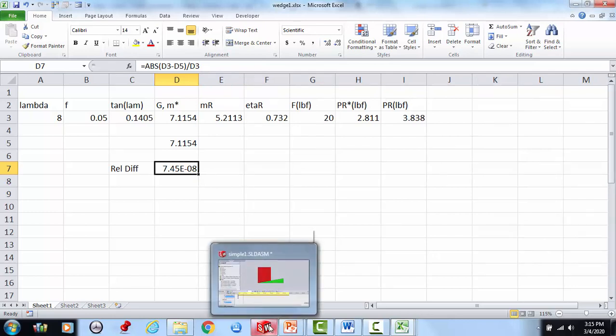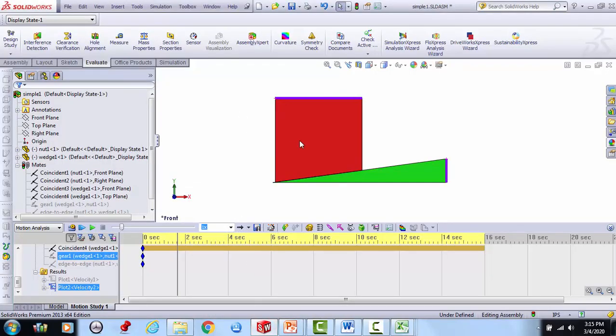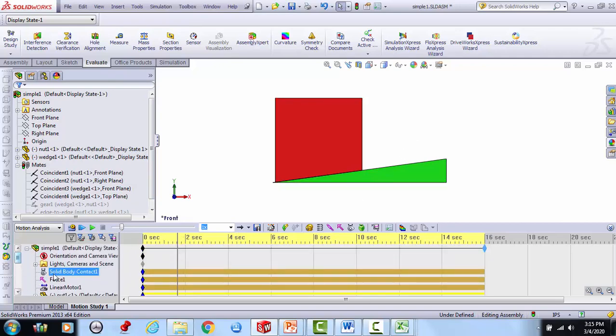Just kind of going back to thinking about what we've done here. That whole gear ratio thing is not because of that gear 1. That's suppressed during the simulation. That is due to the solid body contact and the linear motor you have pushing on your input. That's what's giving us that. The solid body contact is giving us that actual gear ratio. I think that's noteworthy.